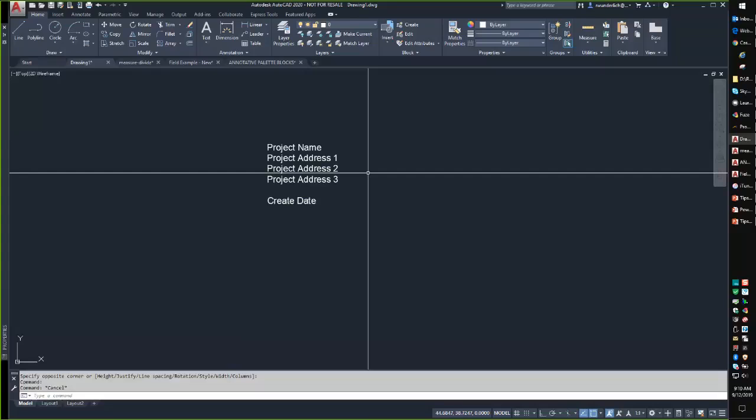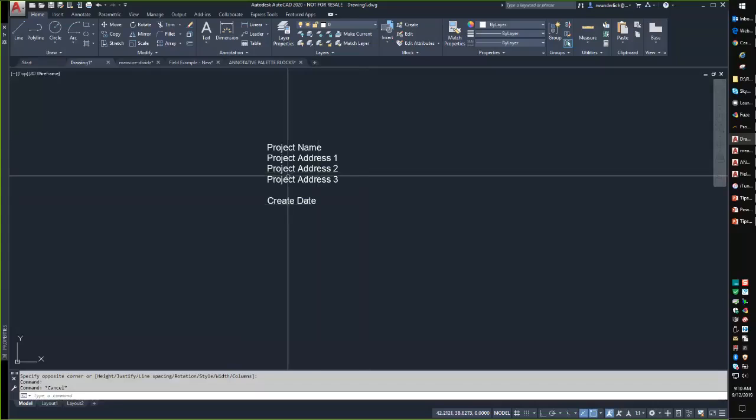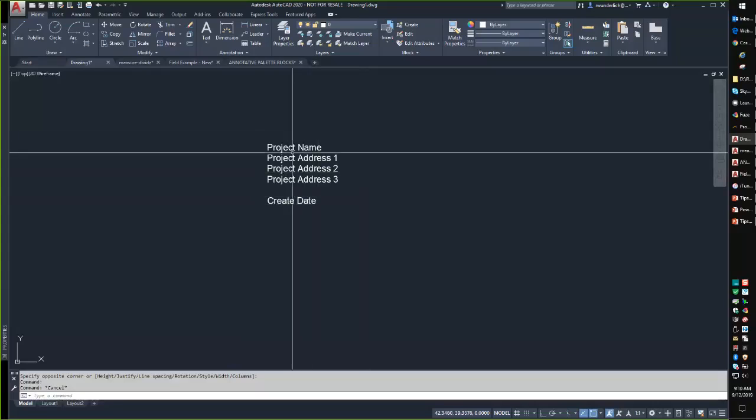Now, these are not tied back to one another. That means that once you've imported that text, it's live in this drawing, and it's not tied back to that initial text file. I like the import text a lot because it allows me to have a running set of notes for a drawing, common notes, things like that, and then I just insert it once into my title block or any of my sheets. I edit as necessary, so that way I'm not retyping constantly, and I'm not copying and pasting from Word.